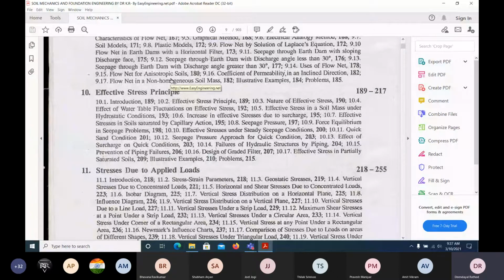So hundreds of thousands of streams of water pass through that particular path, and we will take some flow nets, okay, and equipotential lines where the pressure is constant, equal pressure contours, like we can draw it, and from that, by using Darcy's law, we can find out the discharge happening through the seepage. So these things are required for our design and all, okay.